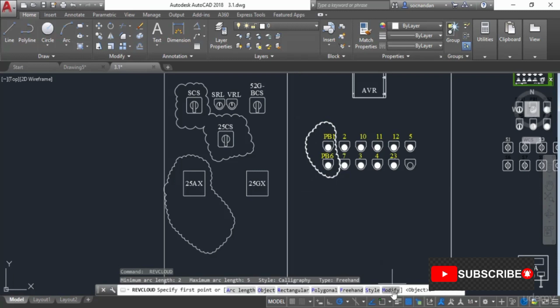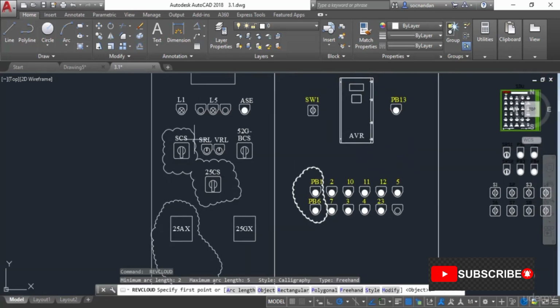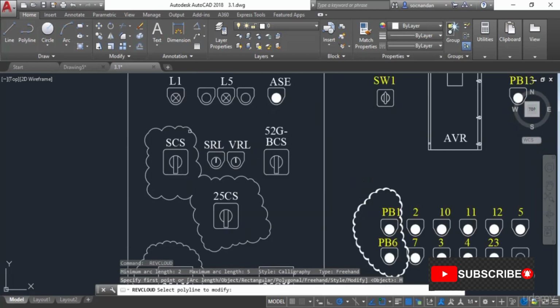So now using this modify option, you can modify any existing revision cloud. For example, let's assume that in this case we want to include these two objects as well in our revision cloud. So for that I can select the modify, and now I'll select the polyline which we want to modify. So obviously this is the revision cloud which we want to modify, and the revision clouds are made up of polylines.